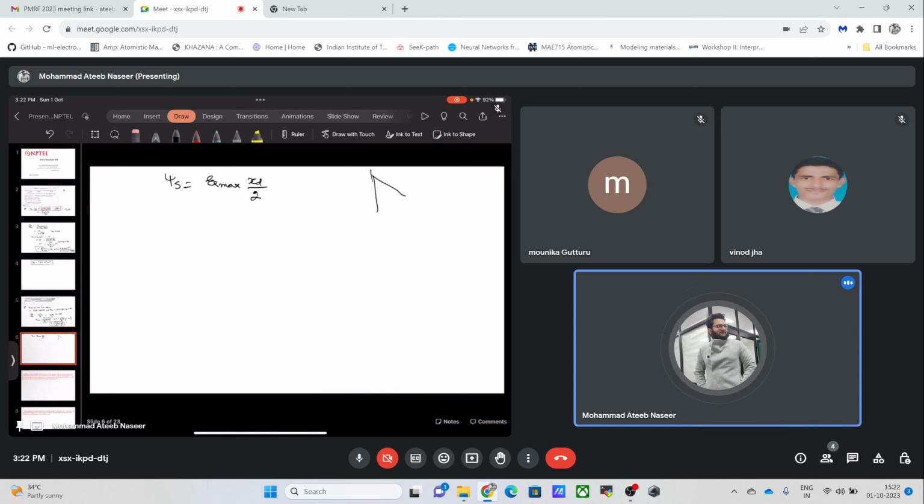If you had seen this x, if this is the xt, this is the electric field maximum value, you would have simply said the area of this is 1/2 of base into the altitude. Base was xt and altitude was the Emax. This was the area under the curve, which is simply the integral. So simply we got this value of psi s to be equal to the Emax times xt by 2.